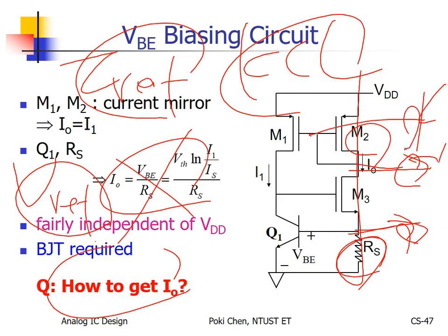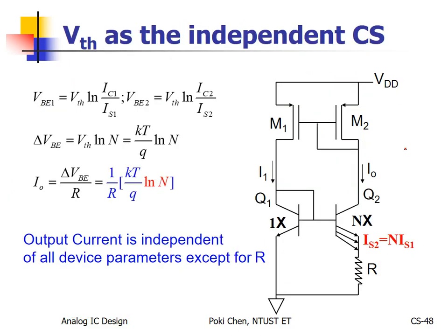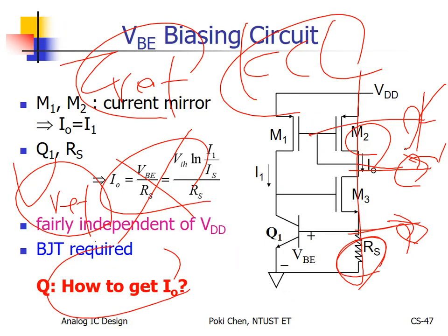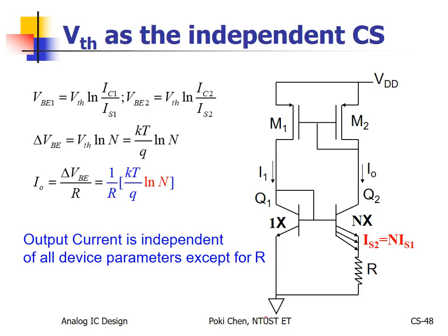It won't destroy the operation conditions. So to tap out a reference voltage, direct tapping out is good enough. But for current, no. You need current mirroring for help. This is the reason why, if your teacher is good enough, he or she never asks you how to get V out. That's an easy question. Direct tap out. Good enough.